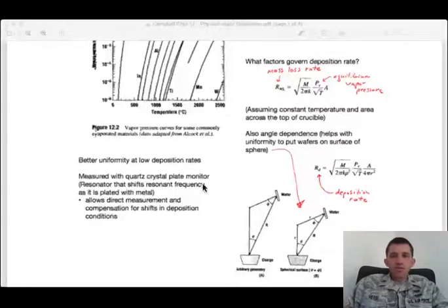And so you can also heat it inductively, right? So you have a crucible, and it's down here. The crucible is made out of, say, some material, say silicon nitride, something like that, and you have coils that go around it, and you drive an AC current through those coils, and it sets up eddy currents inside of your metal charge, right?